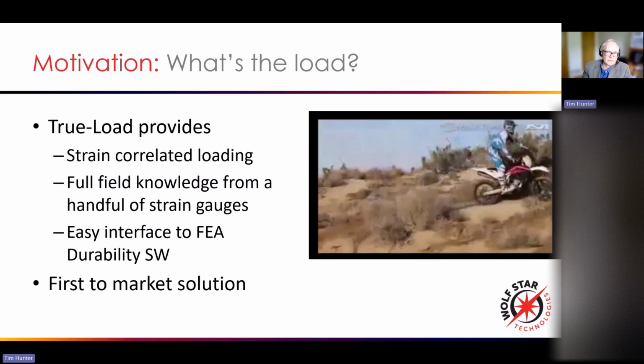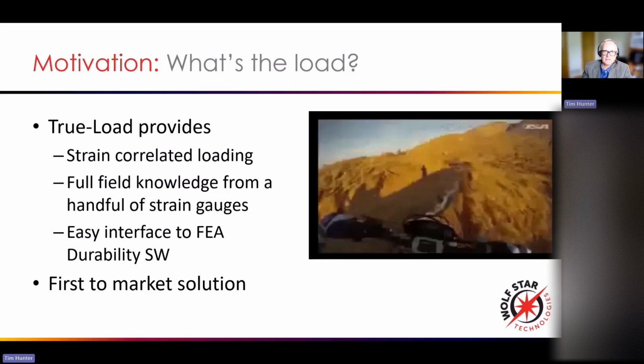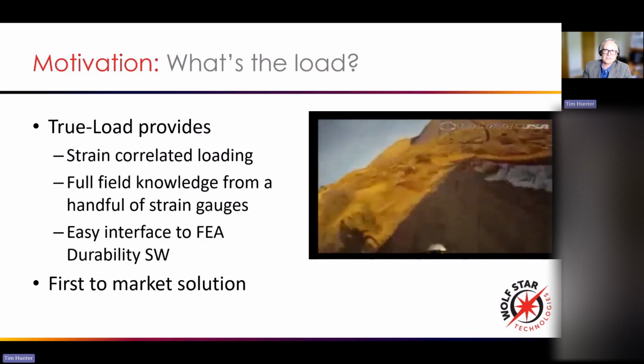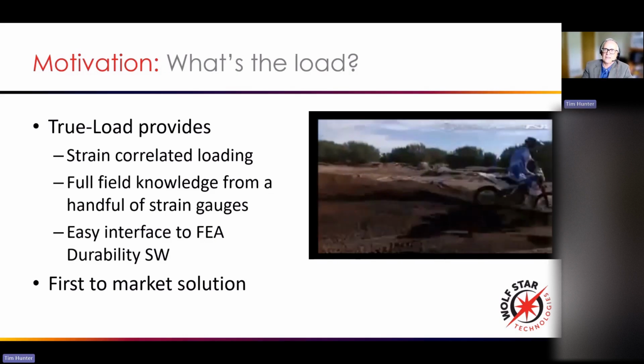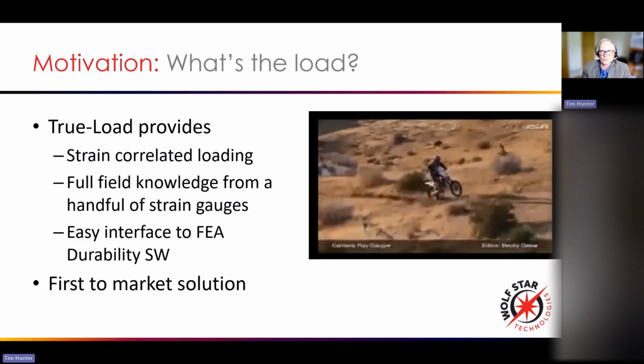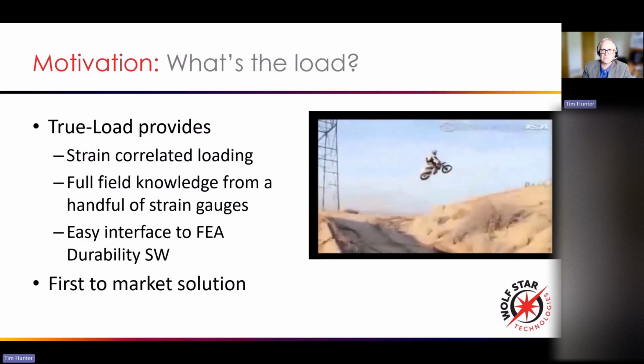And what we're doing is we're leveraging the FEA model, scripting and optimization to get the optimal correlation matrix and the optimal placement of strain gauges, okay? So if you basically leverage the tools you got and use the right optimization strategies, we can do this right and get good answers the right way.